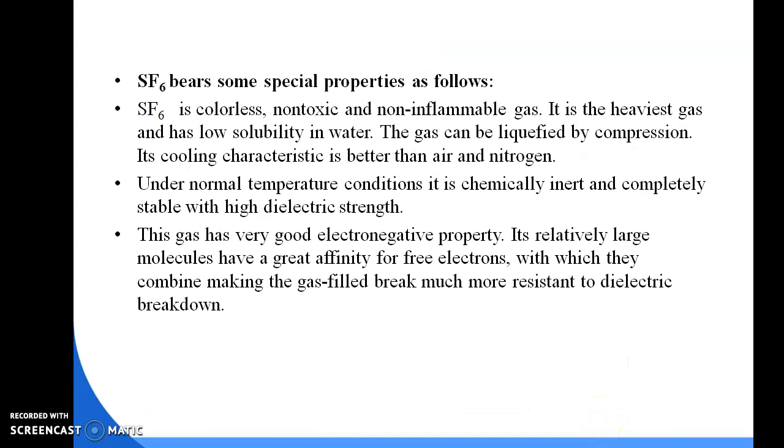SF6 has some special properties. We discussed that SF6 is a colorless, non-toxic and non-inflammable gas. It is a heavy gas and has low solubility in water. The gas can be liquefied by compression. Its cooling characteristic is better than air and nitrogen. Under normal temperature conditions, it is chemically inert and completely stable with a high dielectric strength.